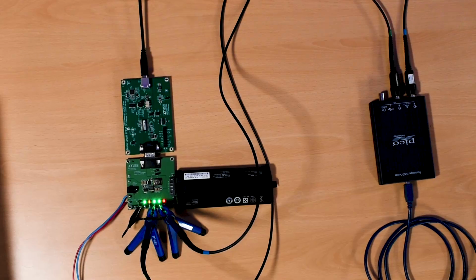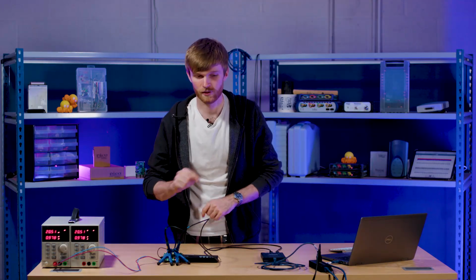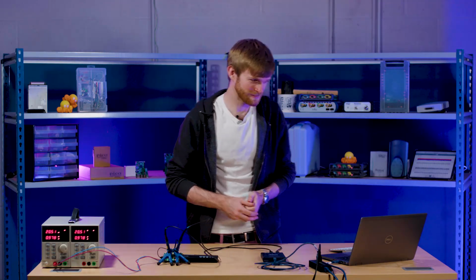So what we have here is another example of I2C. We have a smart battery system with some little commands you can send to it and see what kind of voltage it's at, what temperature it's at, and everything like that. I've hooked up the probes. We've got SDA as our channel A and SCL as our channel B, all plugged into a 2000 series, and then we're going to see what comes out on the other side.